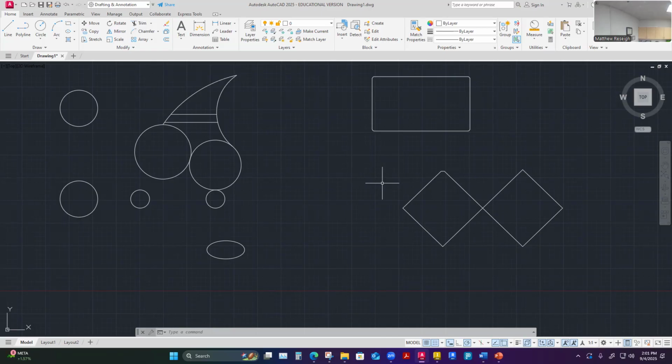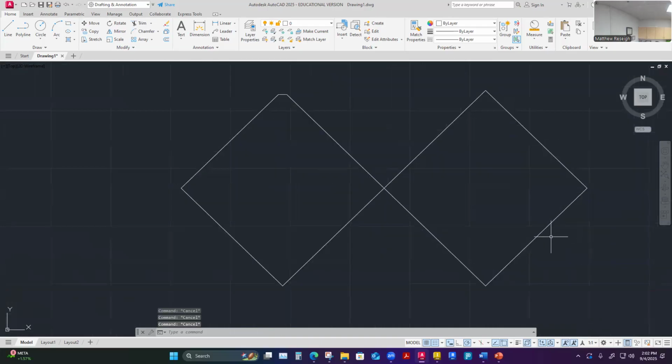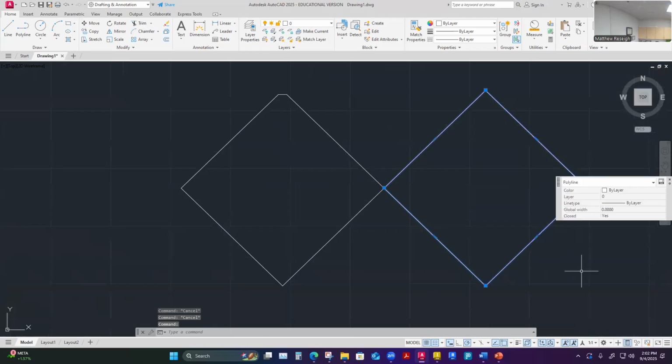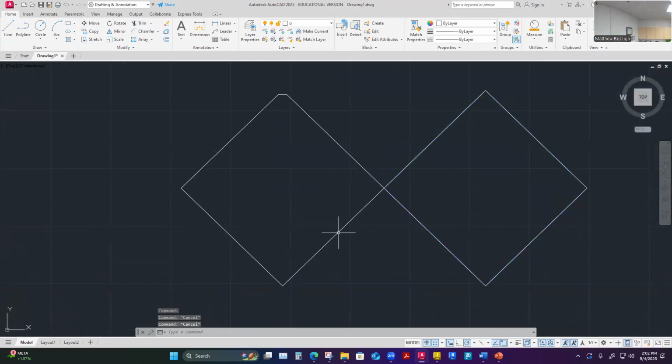And then when I drew the polyline shape and finished, it was all connected. When I hovered over and selected it, it selected the entire thing as one joined polygon. So the explode command is usually used to explode geometry that is already a joined polygon. It's actually to explode joined geometry. Where I could use that is here, this should be joined geometry, right? This was a mirror. So I drew this initial rectangle here.